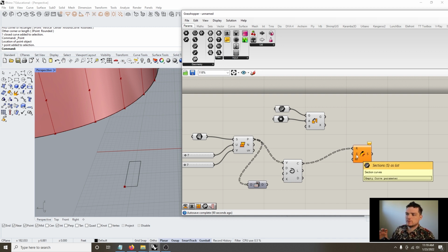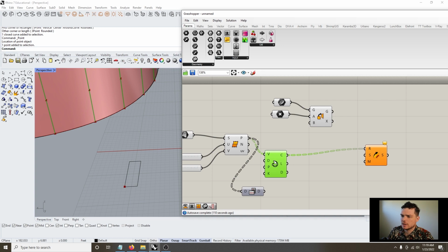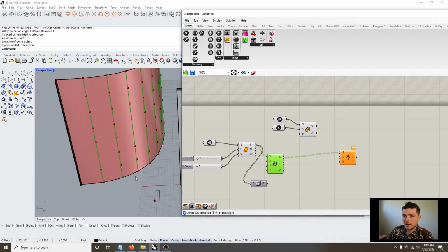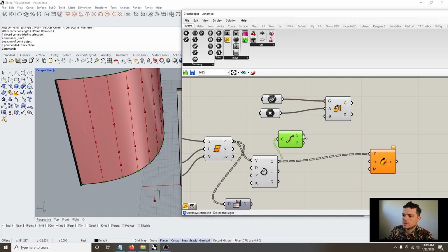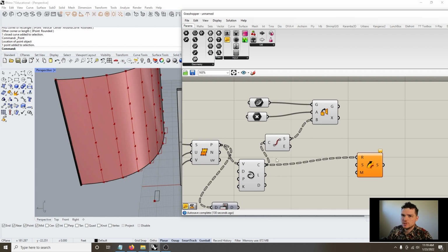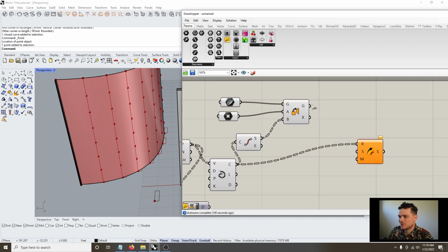Unfortunately, this is not smart enough to orient that sweep, so we have to specify what it's going to reference. We have our curves here, but again, Rhino doesn't really know anything about those curves. It just says it's curves, right? But what we can do is endpoints. Let's type in endpoints, and we can put in our curves, and that's going to give us the endpoints of the curves, which gives us reference geometry that it can take and orient with those points. I know, it's confusing and annoying, but this is the world of Grasshopper.